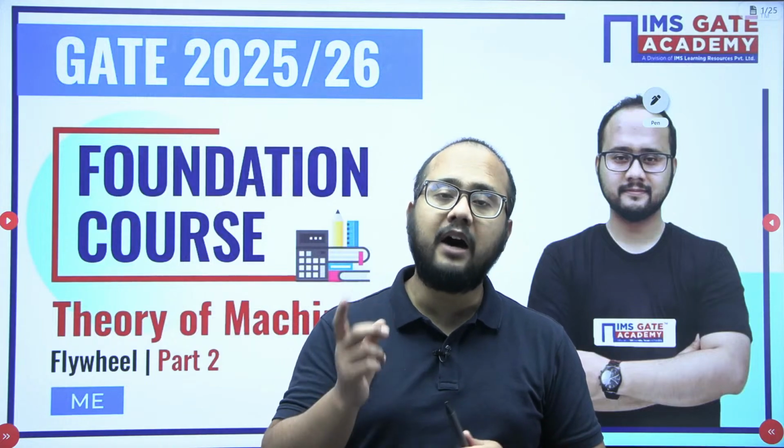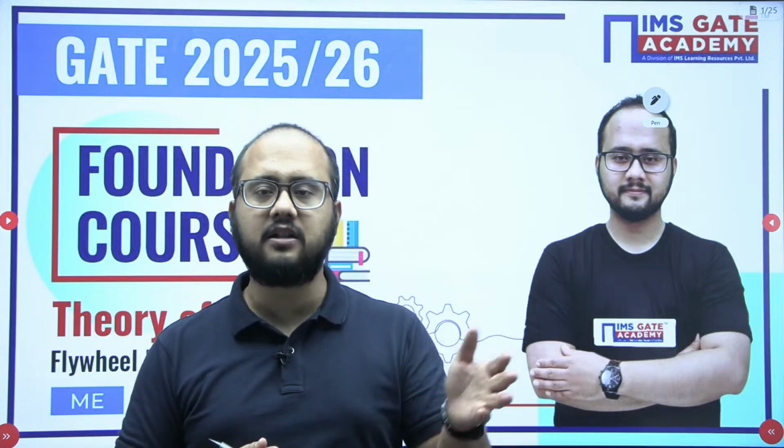So everyone try to understand here, in the case of the flywheel, the main reason why we are using it is because of the fluctuations in the turning moment. Let's suppose we are having a 4-stroke engine. So power we are getting in only one of the strokes. We have suction, compression, the power expansion stroke where we are getting all the power, and then finally exhaust. So out of 4 strokes, in one stroke we are getting power, so there is non-uniformity.